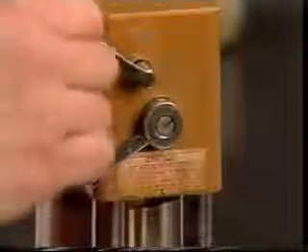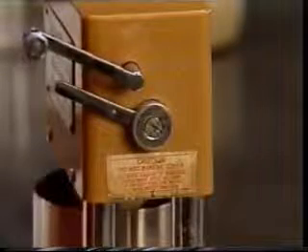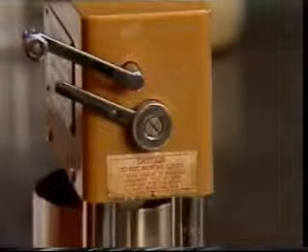Then the speed shift lever is moved to the 600 RPM position and the crank continually turned until a slippage is felt. With the dial reading steady, the 600 RPM reading is taken. Next, the lever is moved to the 300 RPM setting and the crank turned again until slippage is felt. While continuing to turn the crank, the second reading is taken at 300 RPM. Cranking is then stopped and the fluid left to rest for 10 seconds.